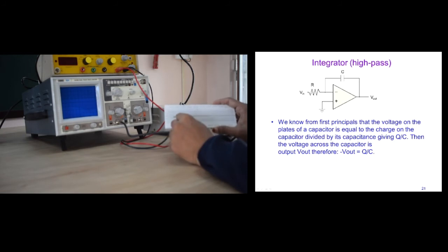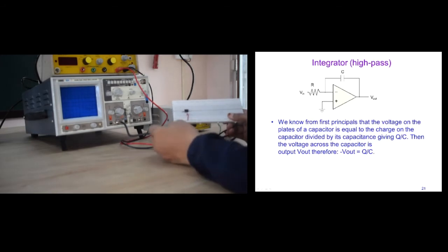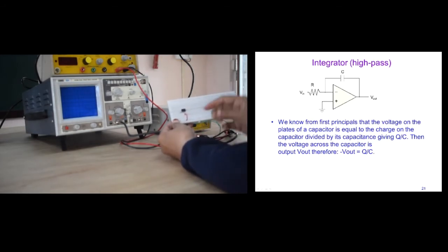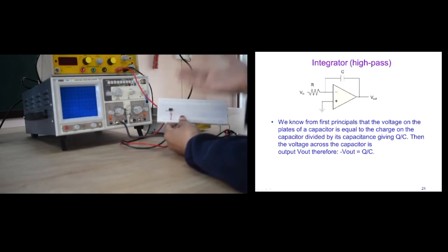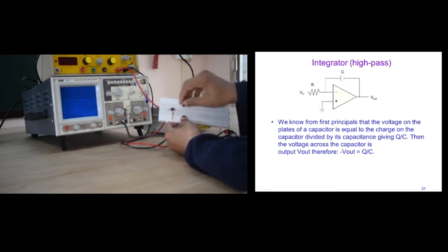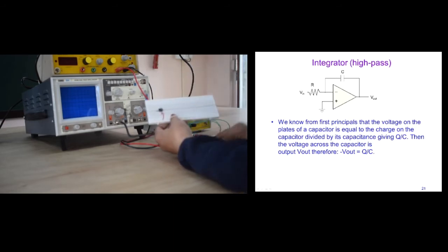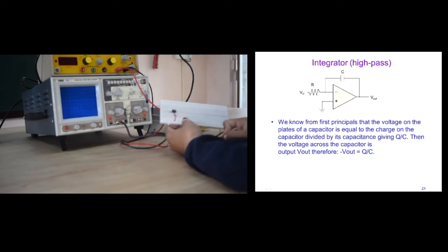We will use the ground line, the horizontal line of the breadboard, for grounding purposes. We are going to connect the capacitor between pin number 2 and pin number 6. Here you will see pin number 6 has 4 terminals we are using upward, so we will use this pin. If we are not able to jump up to that, we can connect the capacitor at another point, and then connect a wire to pin number 6, or otherwise we will make the capacitor jump across the IC.